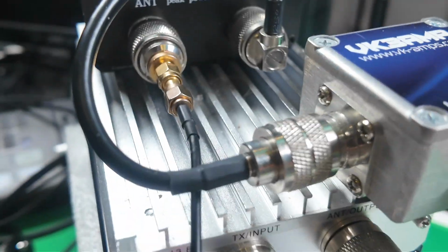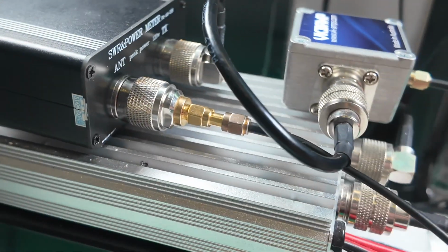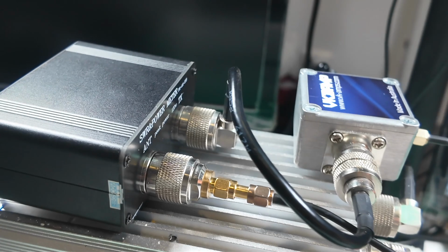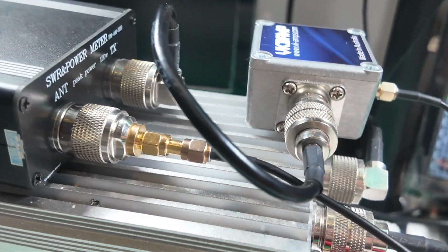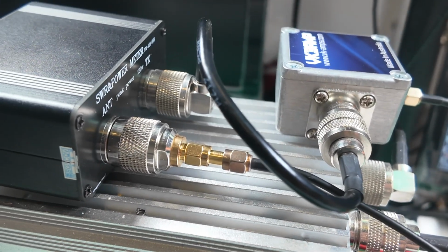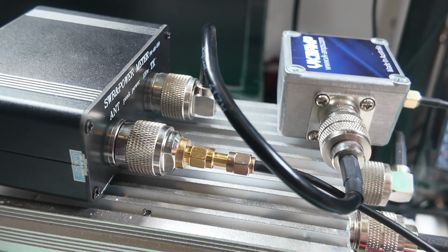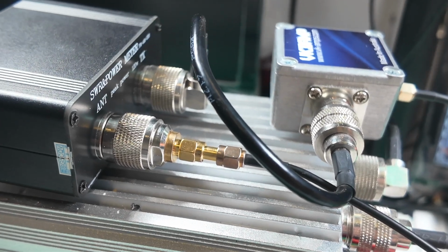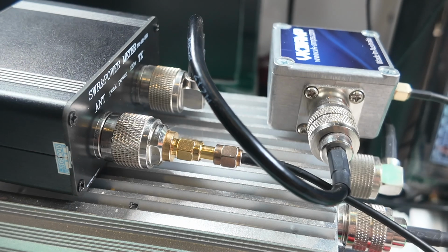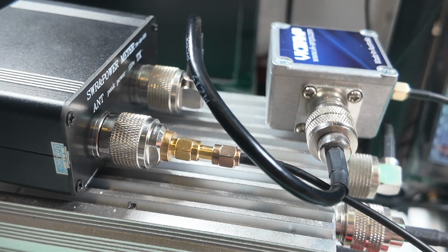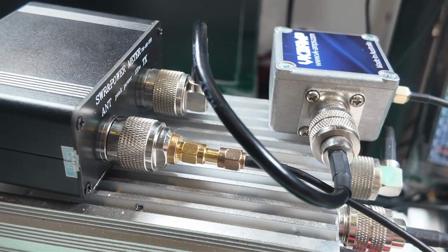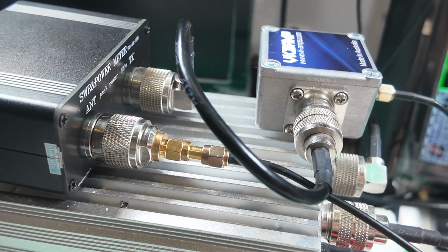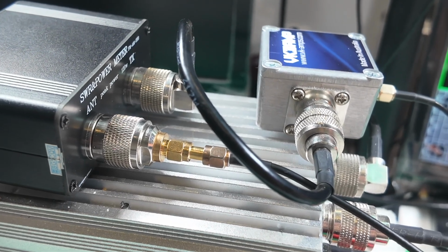The Hermes has circuitry where it'll detect that and process that sampled RF, pre-distorting the output from the Hermes, so the sampled RF, which includes any non-linearities from the amplifier, will be compensated.